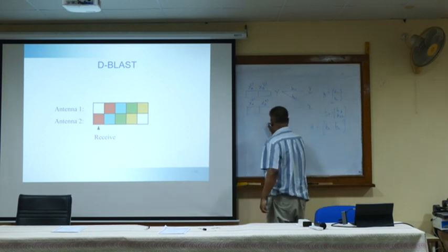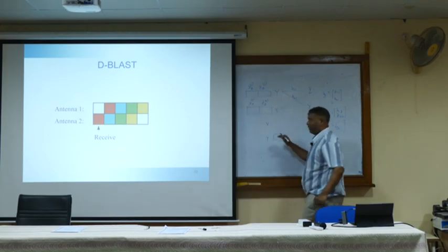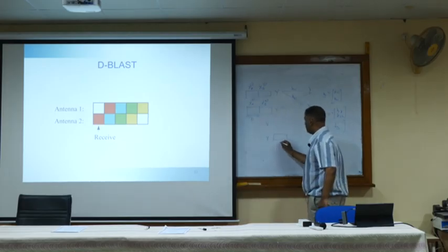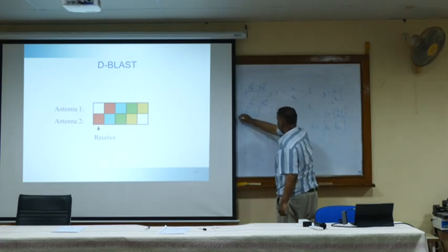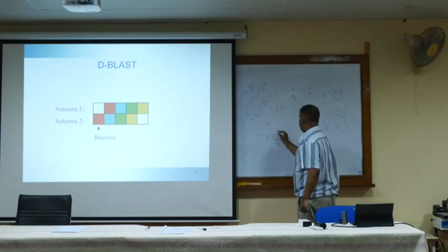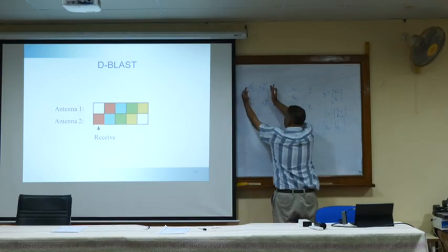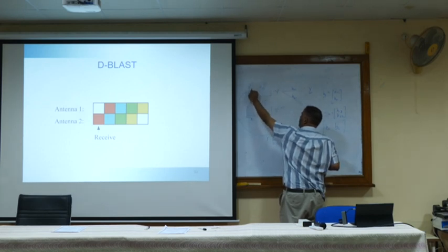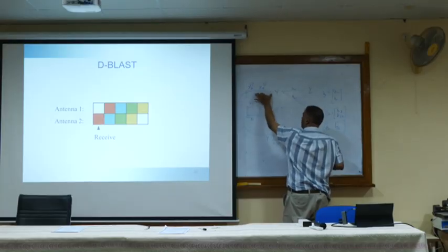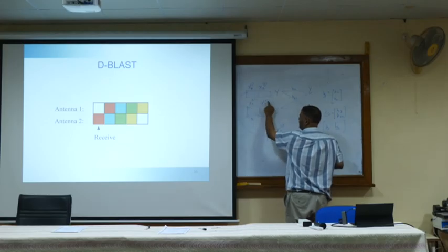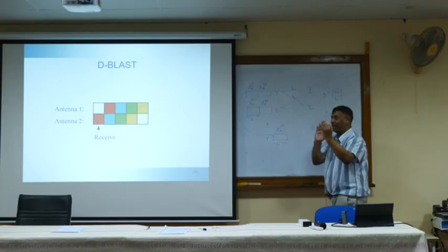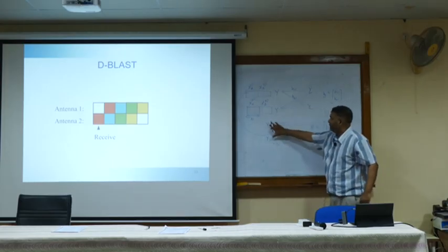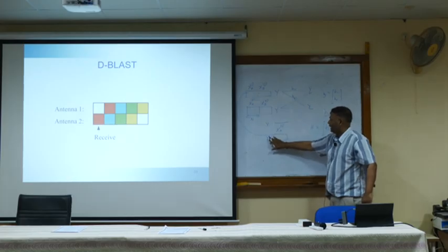So what will happen is, at the first time slot, let's say this is n, okay? So in the first n time, this guy will go through the second antenna. So the entire stream I divided: this is the first stream, the superscript saying the first stream, with an A part and a B part. This is the second stream, the superscript denoting the second stream, also with an A part and a B part. So at the first n time slot, you will send half of the first stream, and the first antenna is not going to send anything. The second antenna is sending this stream, okay?